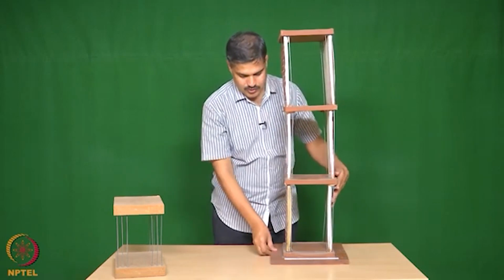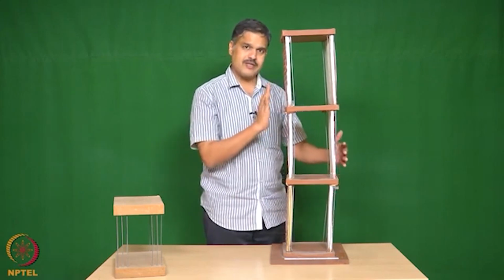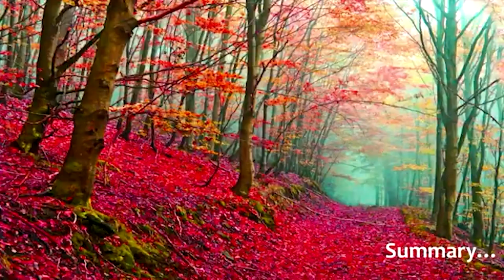If I oscillate it slowly, it will get excited in the first mode. If I increase the frequency, it will be excited in the second mode. If I further increase the frequency of excitation, it will move in the third mode. In summary, in this class we have studied how to formulate the mass matrix and stiffness matrix, how to solve the characteristic equation, and how the solution of the characteristic equation is represented in the form of eigenvalues. Eigenvalue is nothing but the frequency of the structure in each mode: first mode, second mode, third mode.